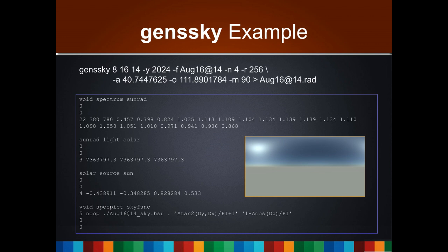And that's an example. It's an equirectangular projection. Yeah. So it's a fisheye, but it's a nice square, and it solves the problem we were having at the horizon because you initially had two hemispheres and it was not blending well. Yeah, so it's pretty easy to use. I highly recommend you try it. And then you apply it to the normal sky dome that you would for GenSky or GenDaylit.